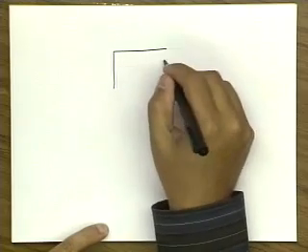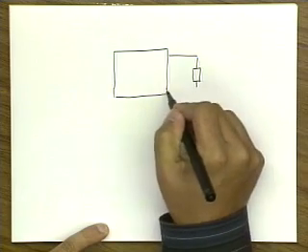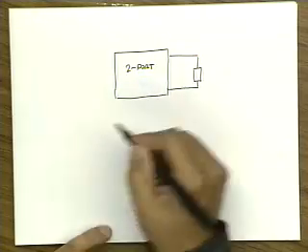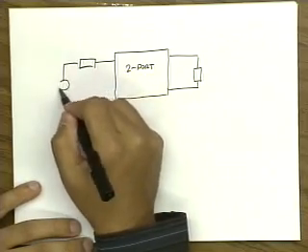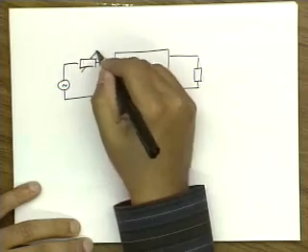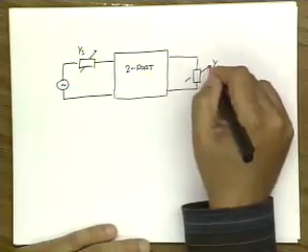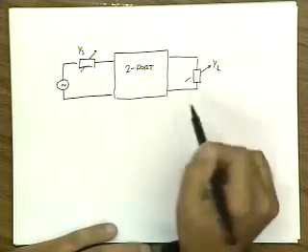Okay, any other questions or comments? All right, so let's recap where we were, and let's try to define the problem again as we did last lecture. The problem that we posed last lecture was we have a generic 2-port that could represent a single amplifier or a chain of transistors, a multi-stage amplifier. And we asked the simple question, what are the optimal source and load admittances such that we can transfer the maximum power to the load? In other words, we maximize the power gain of the system.